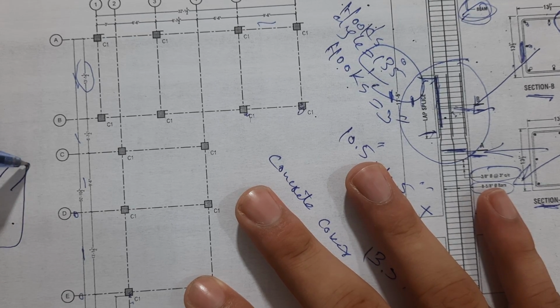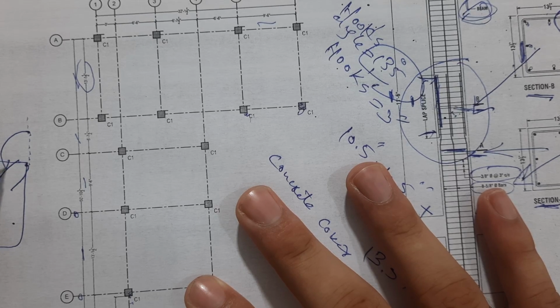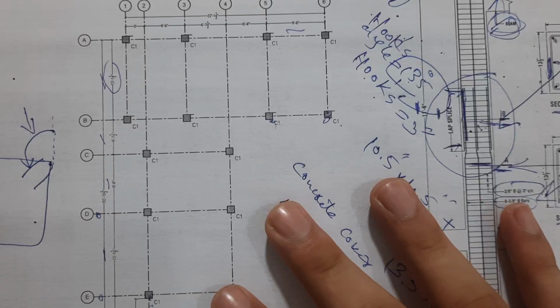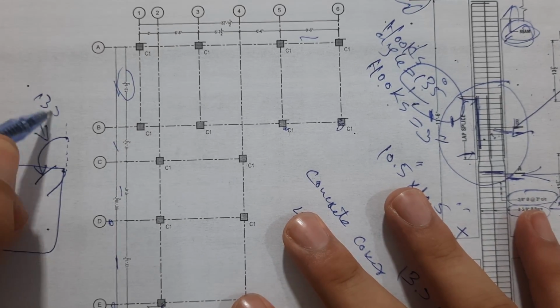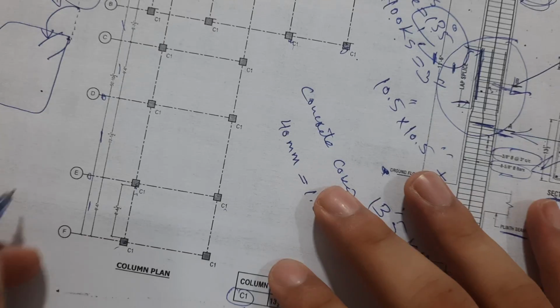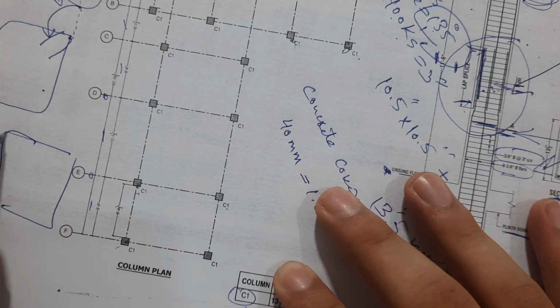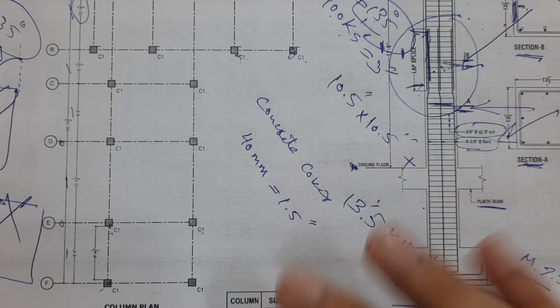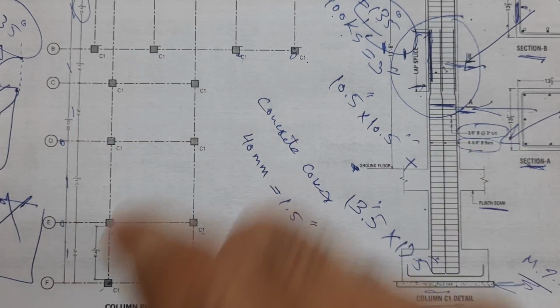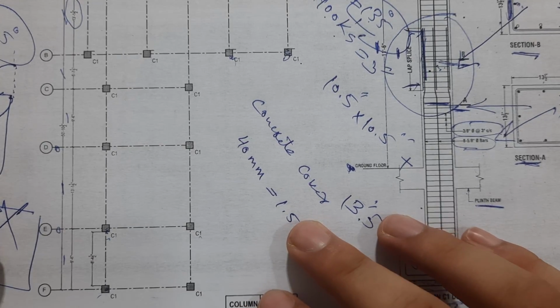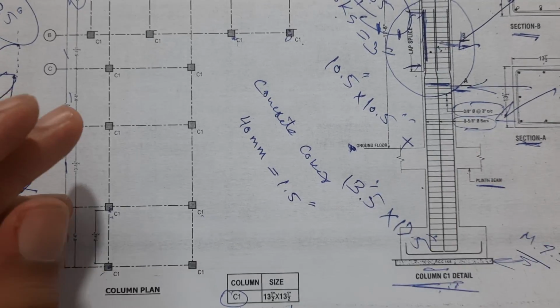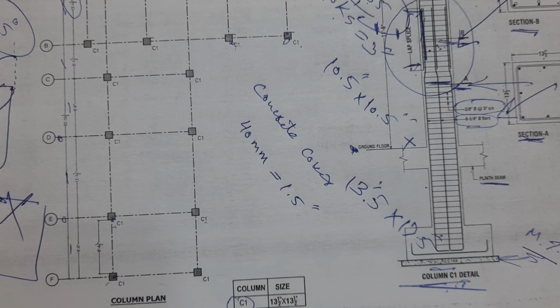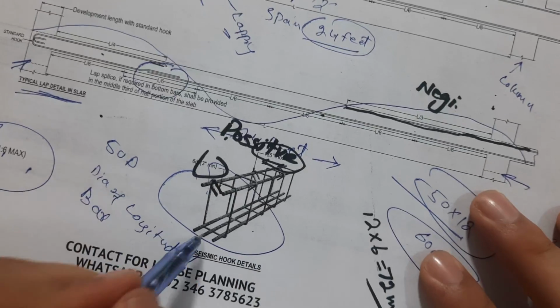Let me show you, this is the dotted line. So when you take an angle, this angle should be 135 degree. Don't provide 90 degree. This is not okay. It can open easily because it cannot resist earthquakes. This is especially for seismic load. Let me show you here in the beam, we already did. Look here, so this is its section.